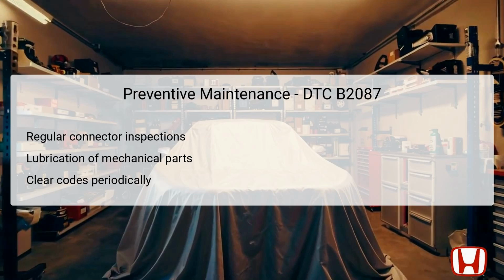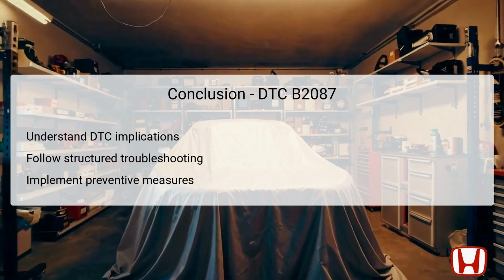Additionally, regularly lubricating the mechanical parts of the sliding door can minimize wear and tear, allowing for a smoother operation. Periodically clearing the DTCs and checking the system can help catch potential problems before they escalate. By maintaining these practices, you can ensure the longevity and reliability of the power sliding door system in your Honda Odyssey.